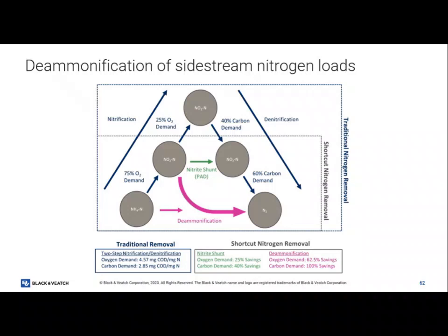You should know why you're sampling. Paul just explained why he's sampling. He didn't say I'm sampling because I was told to. He explained, I'm doing this because I'm trying to control my chlorine dose. He's trying to bleed ammonia to make chloramines. That's what he's trying to do. And so he's trying to reduce his chlorine dose by having ammonium bleed through. But that's a balance. But he knows why he's doing it.